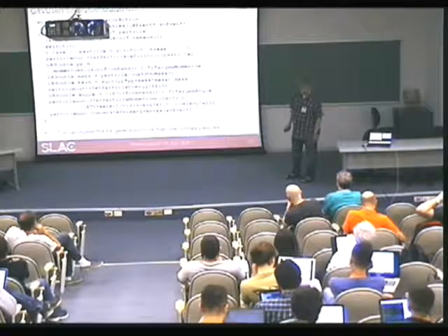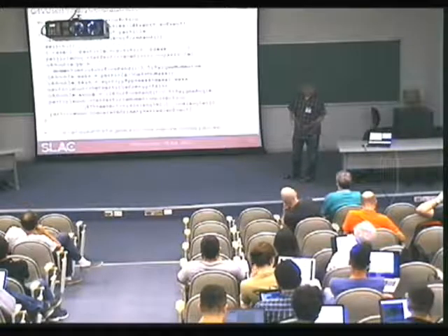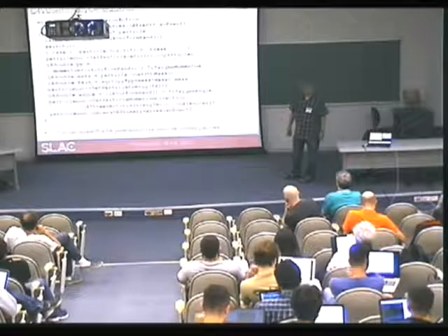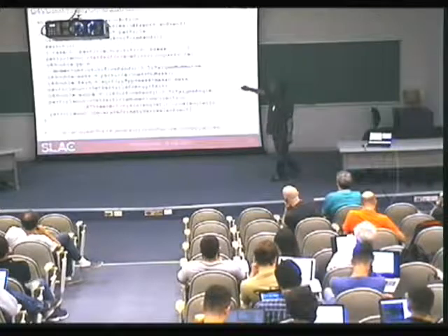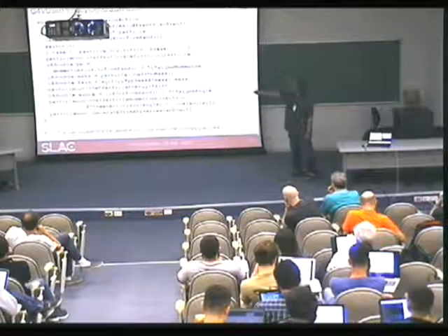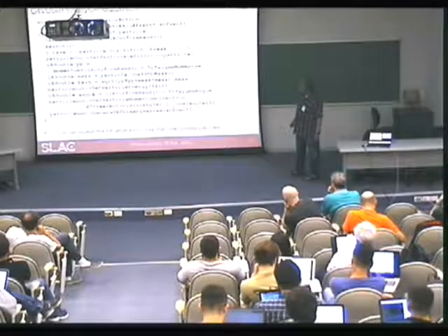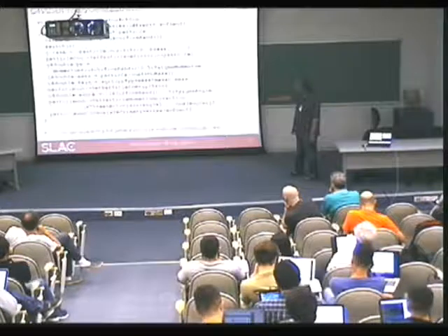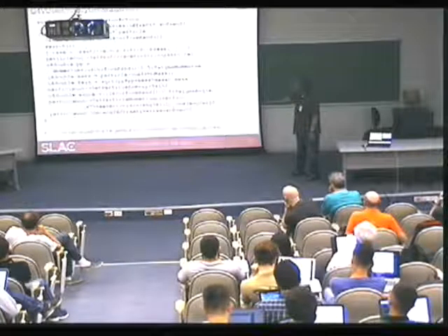If it is 1, I say it's an electron, and so on and so forth. So I'm randomizing the particle type here, event by event, or particle by particle. Okay? Then I set this particle type to the particle gun. Then I randomize the momentum, set it, and calculate the kinetic energy. And this I randomize the direction.